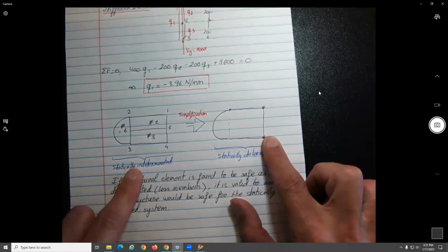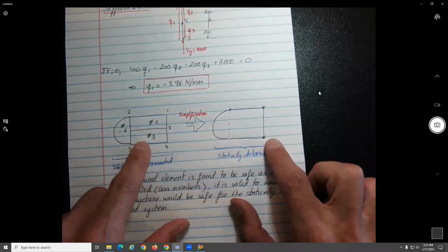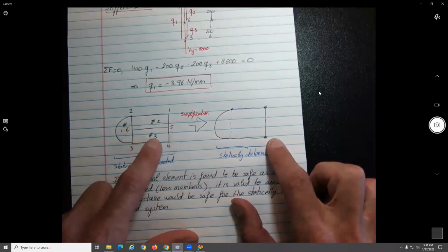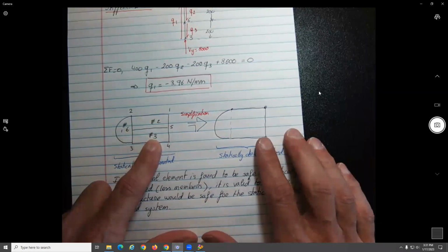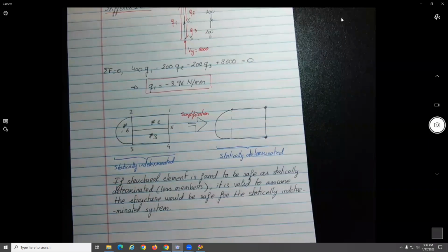Let's say your employer says you need to remove 10% of weight. Then you need to go back into that system and make sure that if you change the diameter of those flanges or stiffeners, it's going to be safe as well. So now you need to get into a more detailed analysis, which would be the statically indeterminate, which is what we'll be doing starting next class. Okay, that's all.